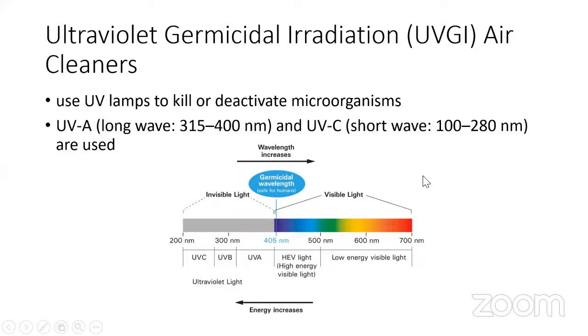These ranges are normally used for the application of ultraviolet germicidal radiation. Normally they use mercury vapor lamps that emit UVC radiation. The wavelength normally is 254 nanometers. Then the sufficient exposure time and lamp power have to be calculated, such that the UV light can penetrate the outer structure of the microorganism, and thus it alters its DNA and prevents replication and causes cell death.